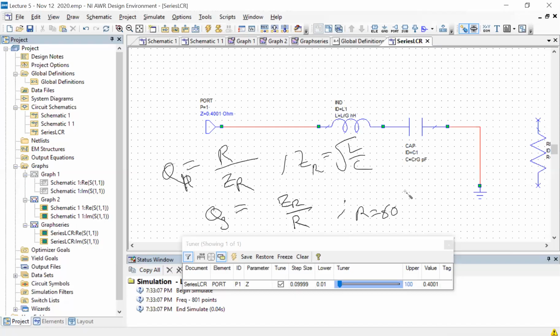Now that is just impossible to design in a microwave circuit, because that means that L has to be very, very large, and such large inductances are just not possible using conventional geometric circuits. Okay, so it becomes very hard to get the quality factor in this kind of geometry. So in any case, we usually don't make lumped element resonators at microwave frequencies.